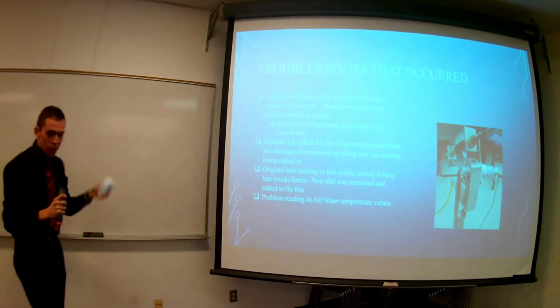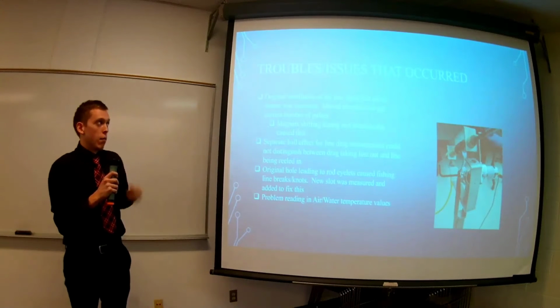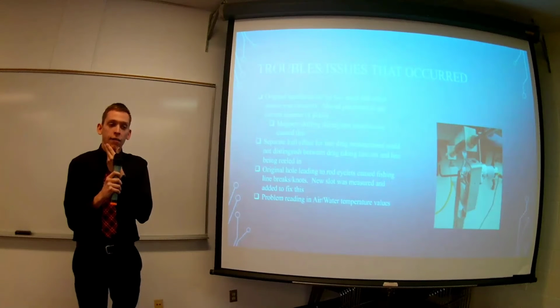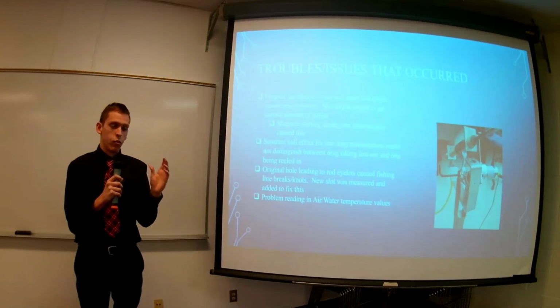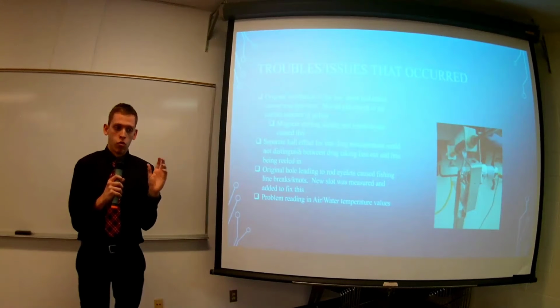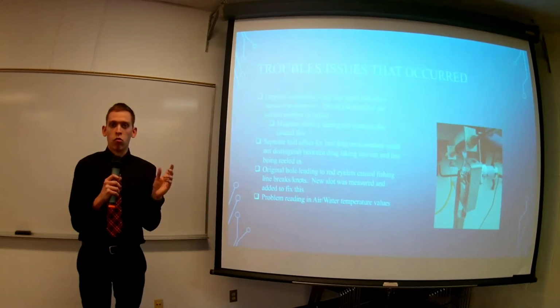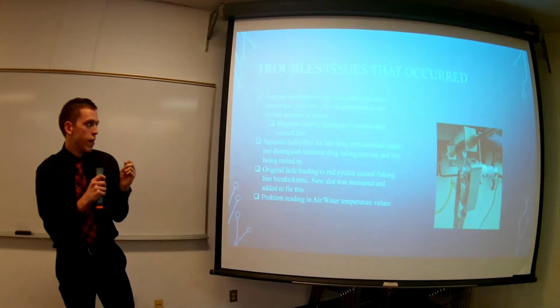All right, so we'll kind of go in depth here a little bit on some of the troubles and issues that occurred along the way. The main one we ended up fighting with was being able to have the magnetic field of those magnets detected by those Hall effect sensors. Turns out after testing, you have to get within millimeters of each other in order to have the Hall effect sensor recognize that the magnetic field is present. So getting it lined up properly, and also to where it would not be struck by any of the rotation of the reel as it's reeling in and out, was a trickier part for us.